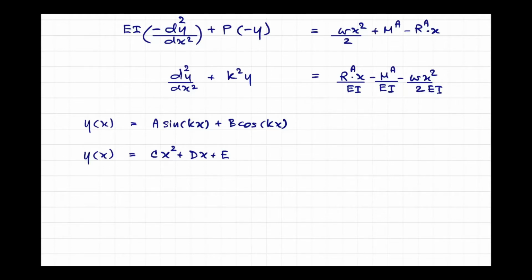You cannot over-conclude the result you have. So the program can incorporate something like plastic hinge formation. First of all, you need to read through the manual of the program and see what the program is capable of. Plastic hinge formation or flexural kinds of nonlinearities can be incorporated.